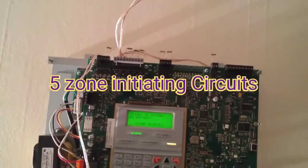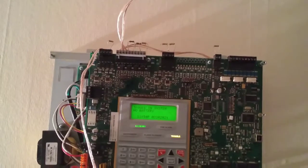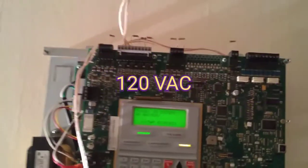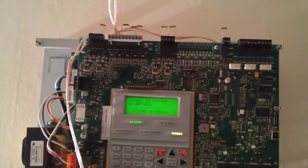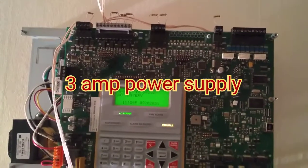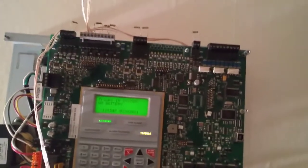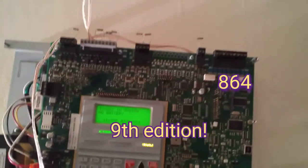5-zone initiating circuits, 4 NACs, selectable strobe sync, 120 volts alternating current, VAC, 3 amps of power supply, and ANSI/UL 864 9th edition. So this panel does code 3, continuous,